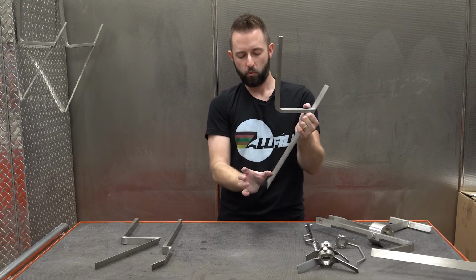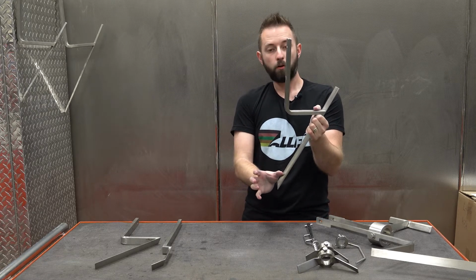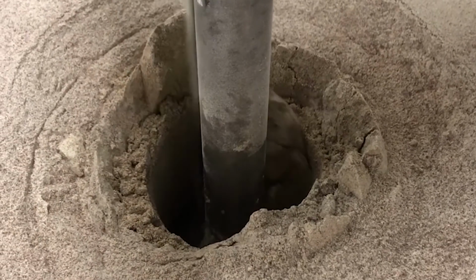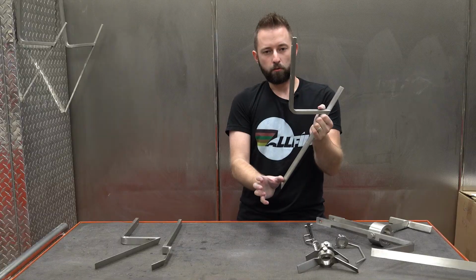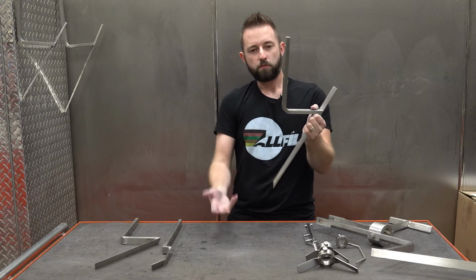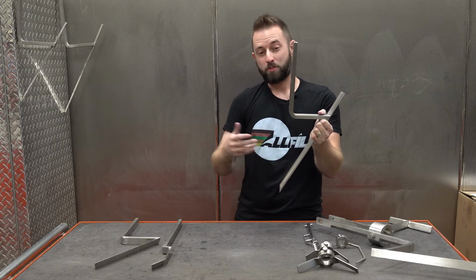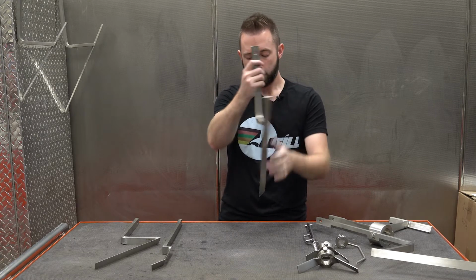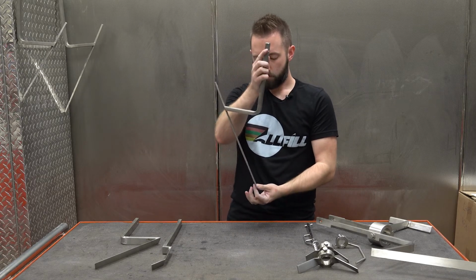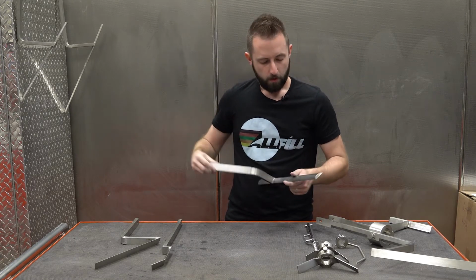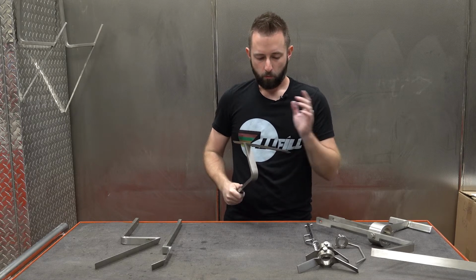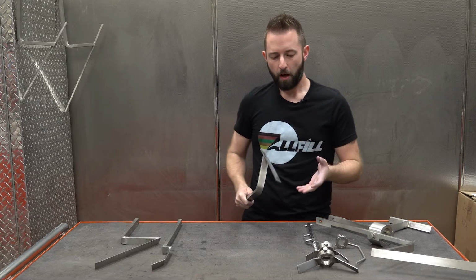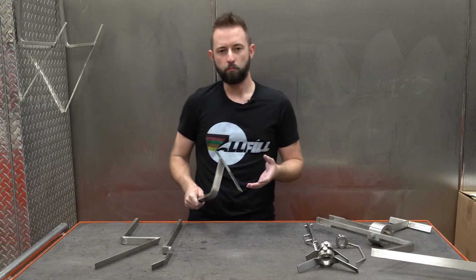When you don't have good agitation, that product no longer collapses towards the center. You can end up with a void or a pocket, which we call a rat hole. Essentially, you starve the auger of product in the center, and this causes fluctuations in your accuracy, fluctuations in how fast you can package product, and you'll see all sorts of issues come from that. So the goal with all of these is to provide the auger consistent delivery of product.